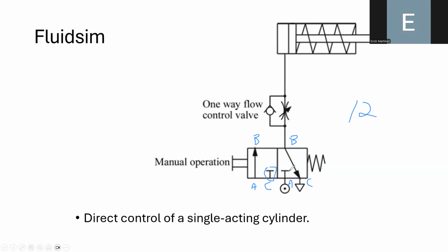So you can observe here that there is no airflow in port A in the second position, but the different behavior is that now the air is moving from port B to port C. Okay, in fact, this is the symbol of an air exit. So this means that the air is exiting through an air exit right here when the piston is retracting. Okay, because the air moves from this region through this connection or via this tube, and then the air is pushed into this region and is exiting to the environment.